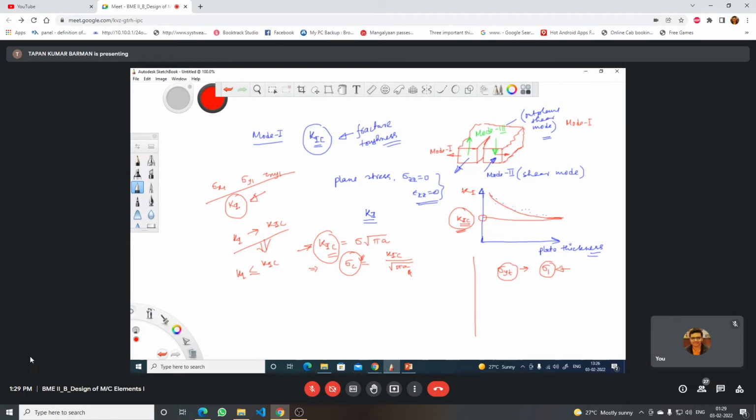But here, physically, what does it mean? If I apply, say, P amount of load in the material, say this is my material, the stresses will be developed here, and the induced stress should be less than or equal to the strength of the material, right? If it is brittle material, at that time it should be equal to sigma ut, ultimate point stress.